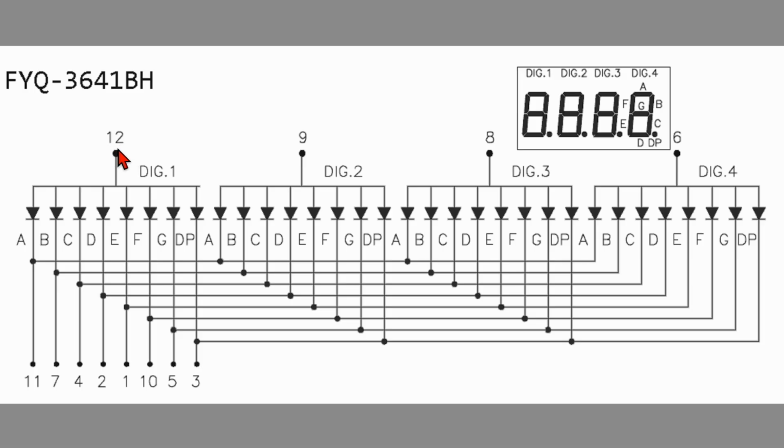If you were to just connect pin 12 to 5 volts and say pin 4 to ground, you'd have too much current, and this particular LED here would get fried real quickly. But by putting a resistor right here and right here and right here and right here, however the current flows, it will be going through the resistor.